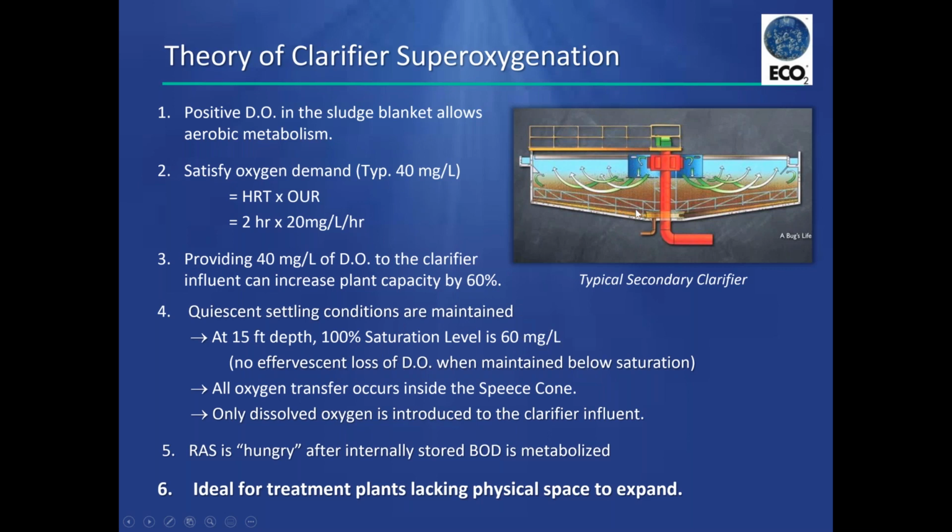So that the water is still undersaturated with respect to the pure oxygen dissolved. So we are preventing any effervescent loss of the DO when we go up to these very high conditions here. And the reason for that is we are bringing the mixed liquor in with all of the dissolved oxygen dissolved. No bubbles are involved in this.